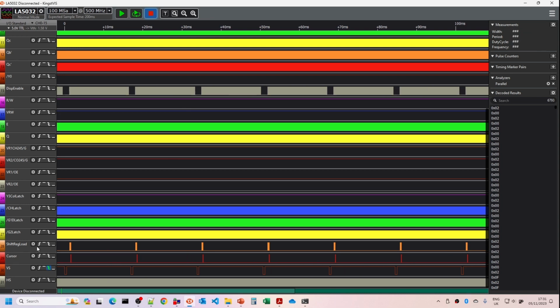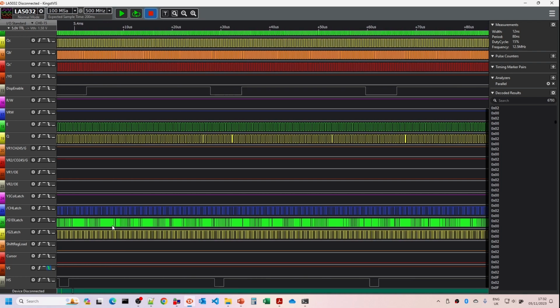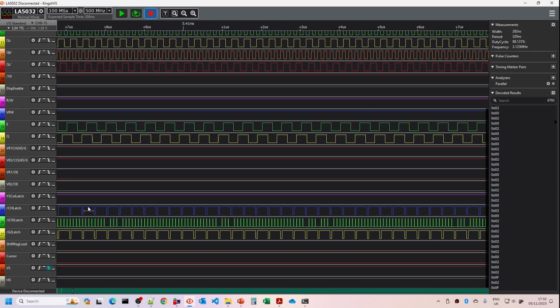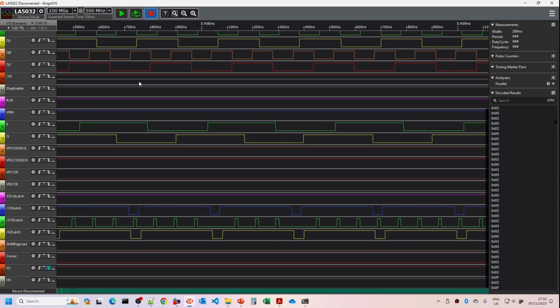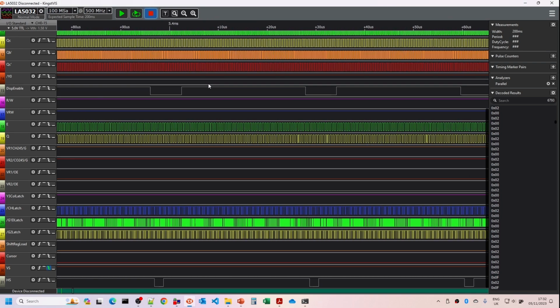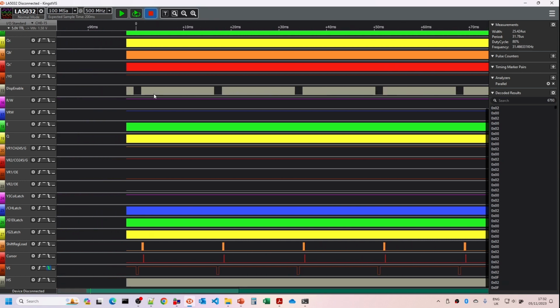And these are all the other various latches and things that we'll be looking at. So these are all the character latches used for both the character mode and the high res graphics mode. The G1 and G2 latches are used mainly for the color mode, but in the character and high res graphics mode, the G2 latch mirrors pretty much the character latch there. So these are all the signals that we need to coordinate, and obviously as we start to update the video, we have to really coordinate when these latch signals are interlacing with the memory write signals in here.